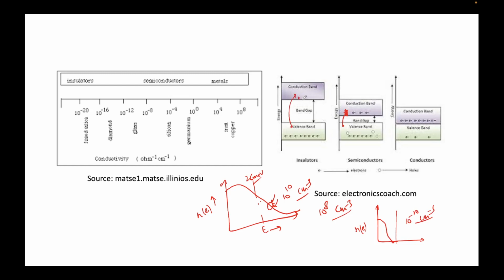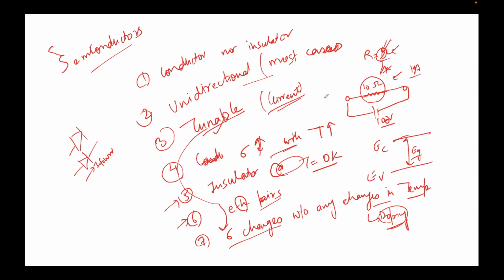That's why in insulators like silicon dioxide, like Al2O3, which we also call dielectrics, and like silicon nitride, these are very famous dielectrics or insulators, we see no current. This is the reason that we were saying here that it's insulated at 0 Kelvin.